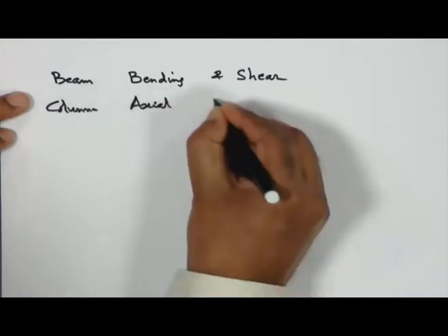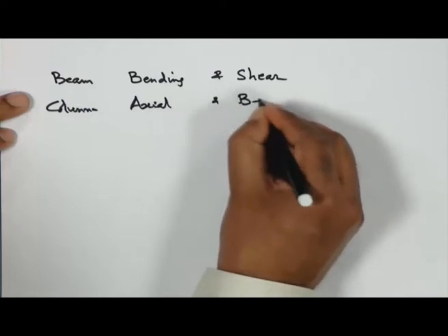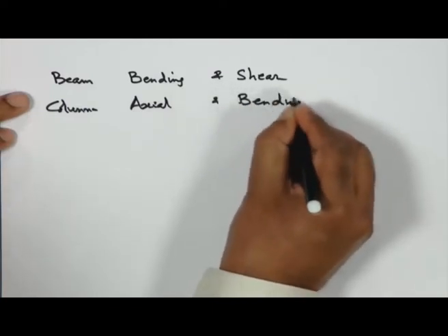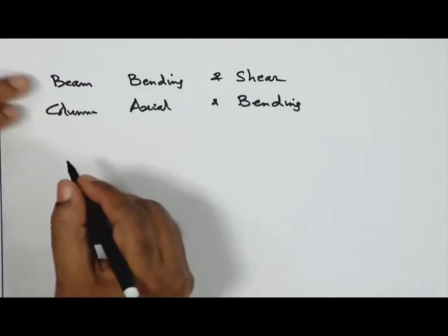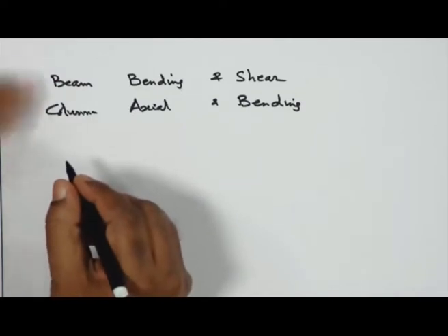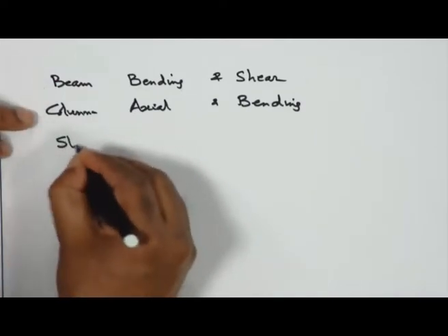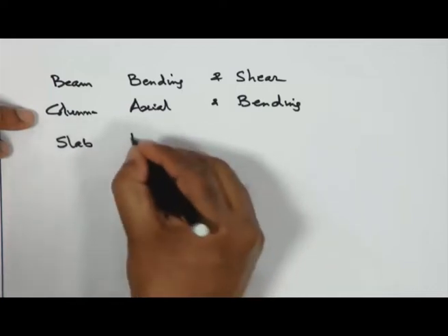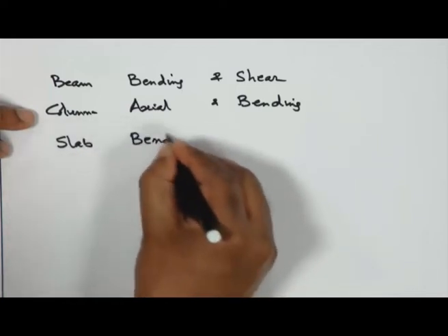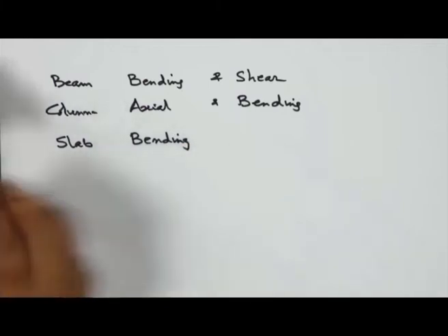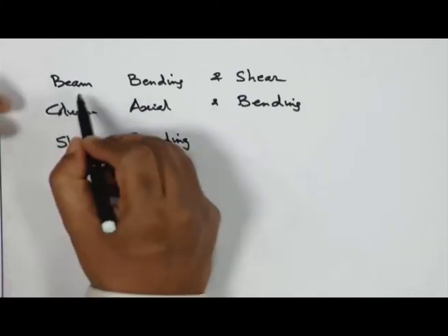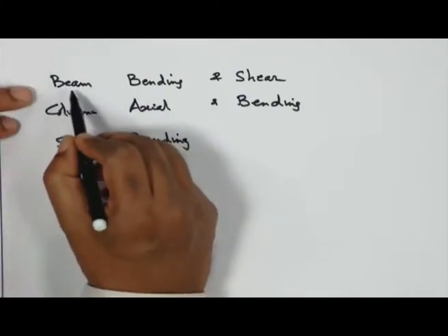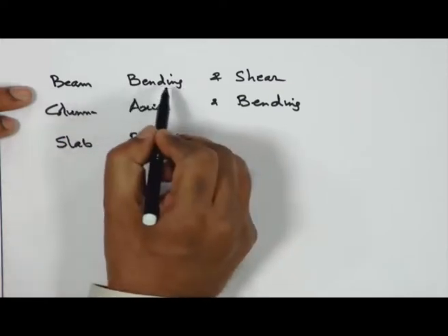We always prefer the under reinforced section, because concrete fails fast. We do not allow that, because if concrete fails, it will fail immediately in material and time, without warning. Whereas in steel, it may yield because of the limiting strain. And we prefer the under reinforced section. So this is the order here.